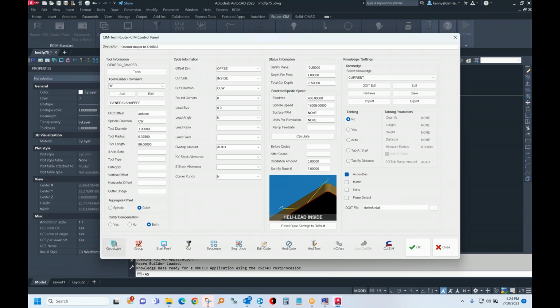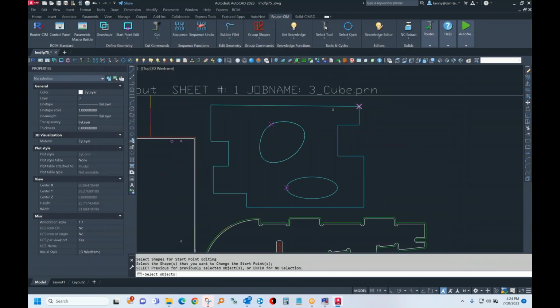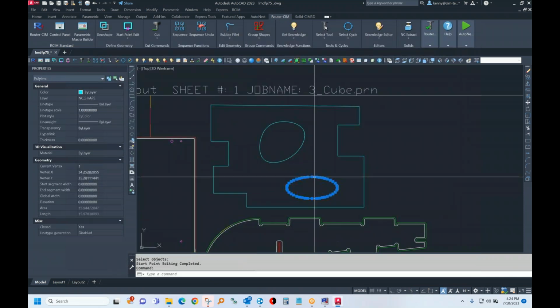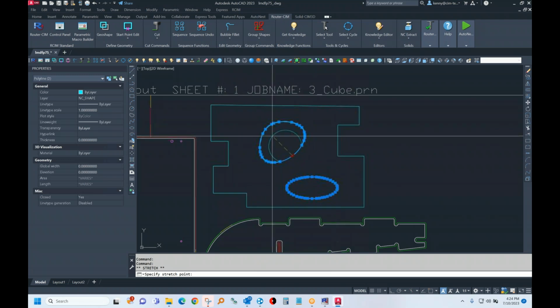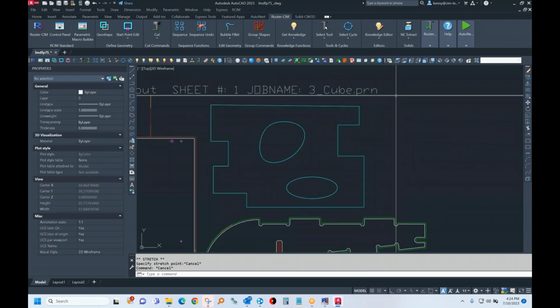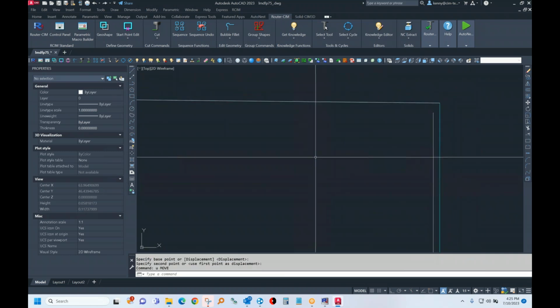There's a step here called GeoShape. It'll take whatever I select and glue it together and fix the problem areas. So this one had a little gap. I'm going to put my start point up here. And at this point, too, it converted the ellipse and the spline into arc segments. So I've got these as all arcs now. It's much smoother to run that as arcs. And it's also a closed shape now right over top of the old one. It fixed that problem area.